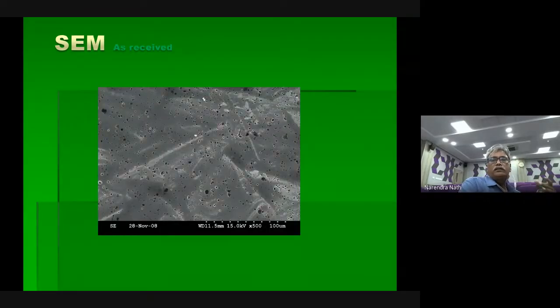And this is actually very typical. Titanium nickel is very typical. So whatever you are seeing, these are all not holes. These are all precipitates. It is like this. Because of polishing, they go, and it looks like a porosity. But it is not the case. This is because of our poor polishing and etching. So wherever you are seeing that, that is not the case.